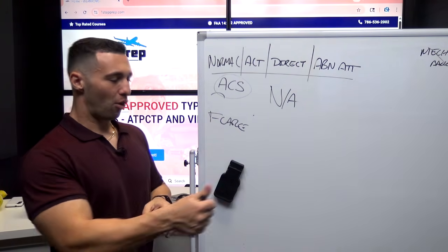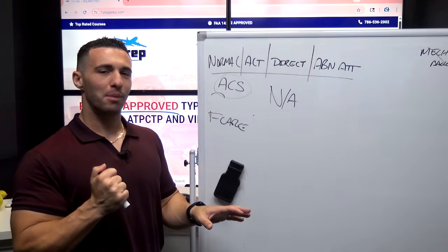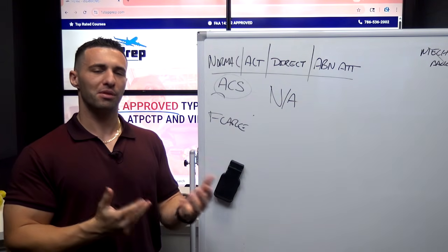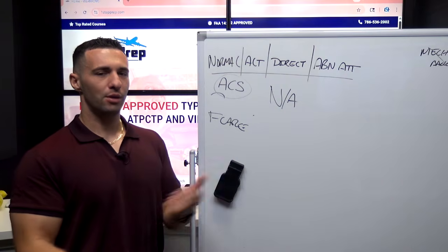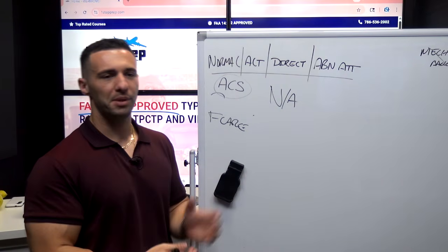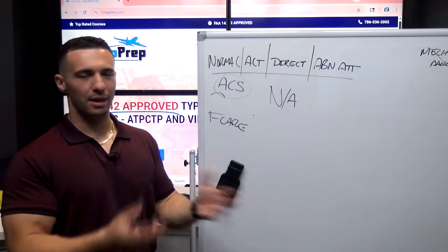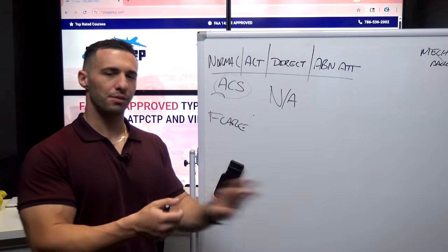So it's all this input, and you very well may be applying a considerable amount of stick input, and you're like, man, how come the nose isn't coming up as much as I would want? And then all of a sudden you hear positive climb, you command gear up, the gear comes up, the airplane realizes it's not landing, it cancels out the flare mode. All of a sudden the flare mode's no longer there.